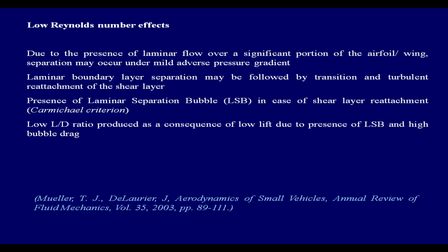One thing that you always should do is choose the airfoil section which works better in the lower Reynolds number regimes to begin with, and then put add-on measures which can perhaps help to further improve the performance. It may not be just the lifting surface alone, it may be the entire configuration which you may have to redesign, rethink.